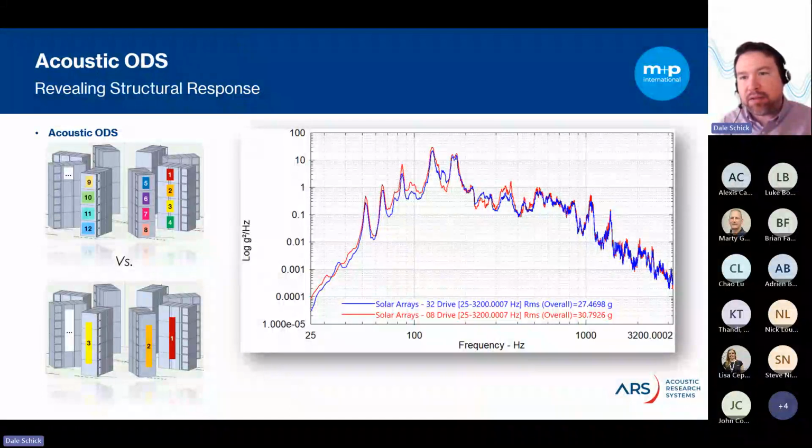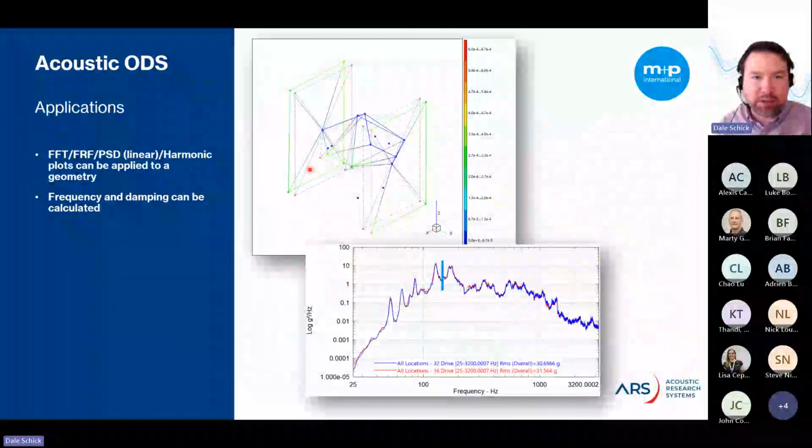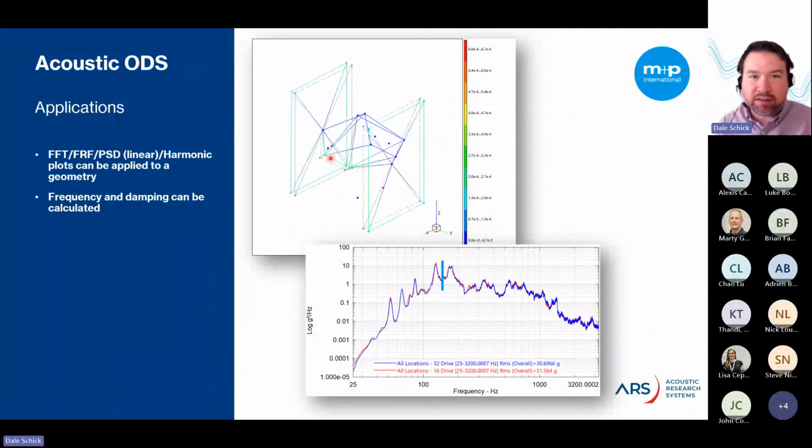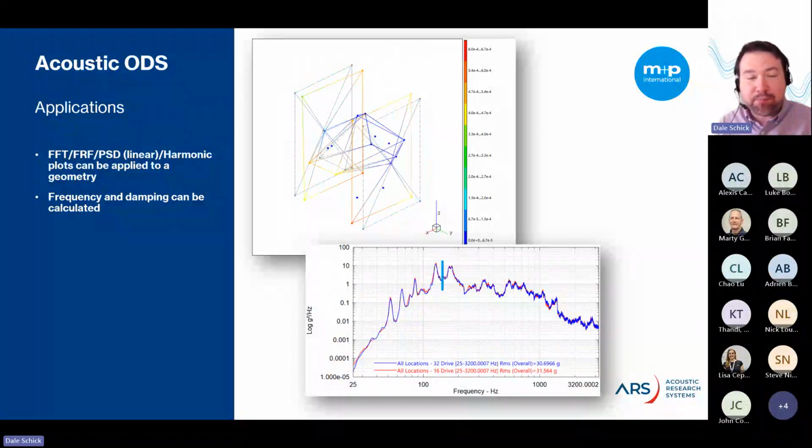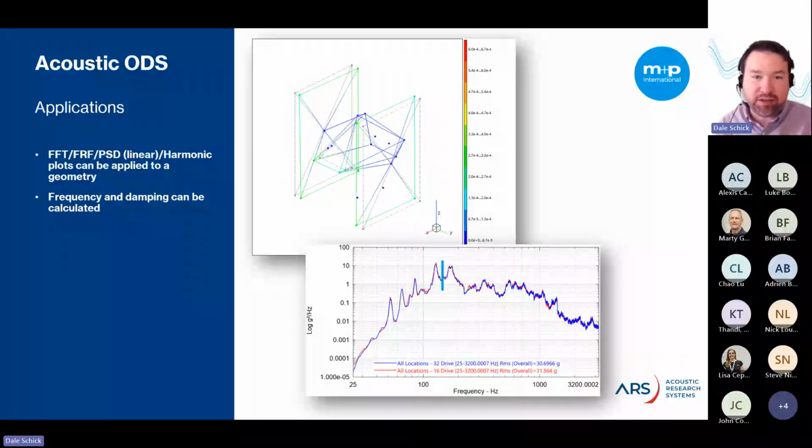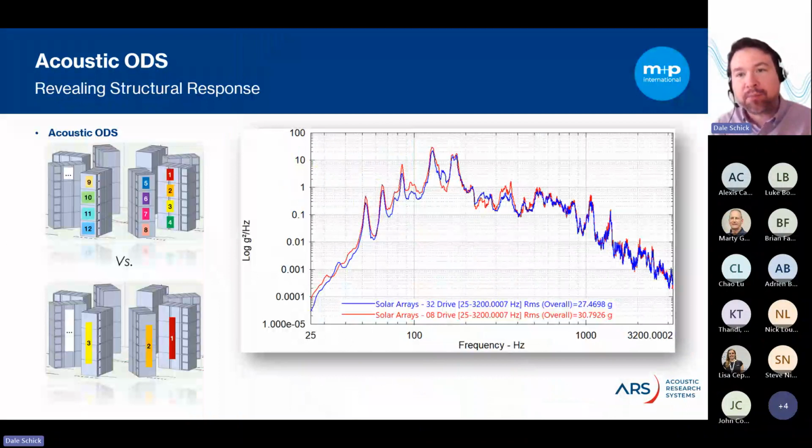So we know from that previous impact modal test that the 148 hertz mode is a coupled mode between the two solar arrays. If we look at the animation again, you can see the two solar arrays here. I swear this is not a TIE fighter from Star Wars. This is a real test article, and it's actually a big cylindrical structure, but this is just where we put the accelerometers. So you get this little Easter egg there. But we do know that those two big panels are solar arrays, and that they have this coupled mode that's excited by any general excitation at that particular frequency, right?